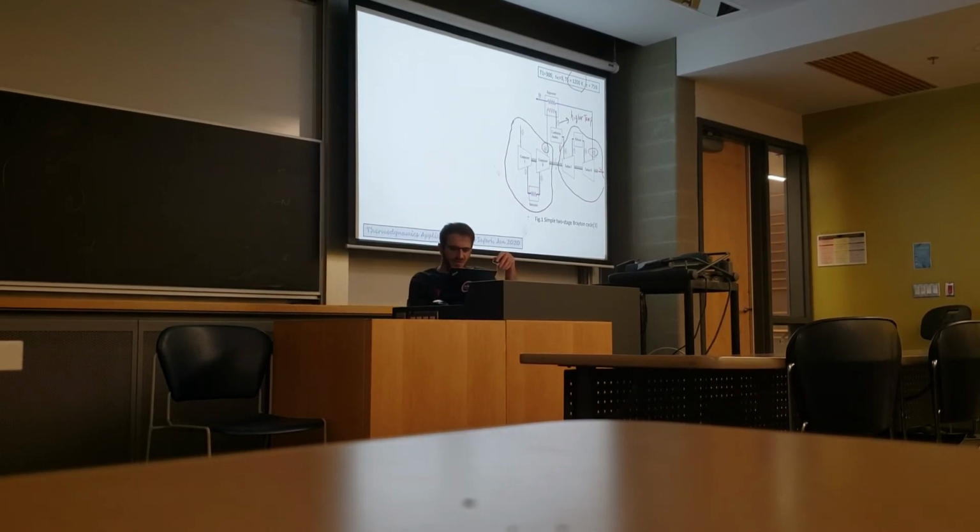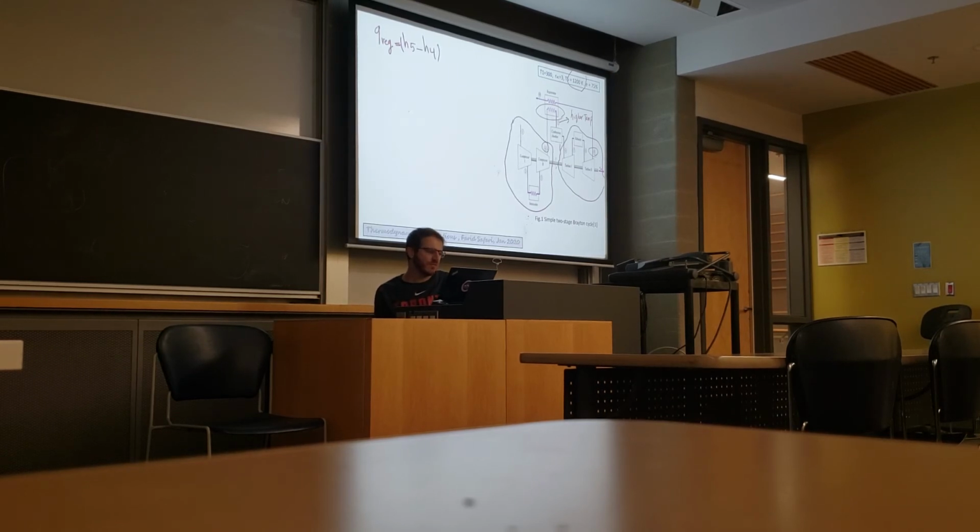So we have here, for the regenerative case, Q regeneration. So this is the Q regeneration, means the Q that we save. So basically the amount of energy compared to the previous case that we save is H5 minus H4.